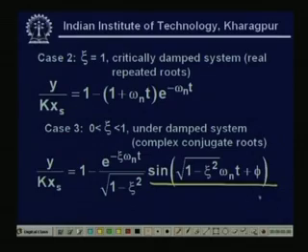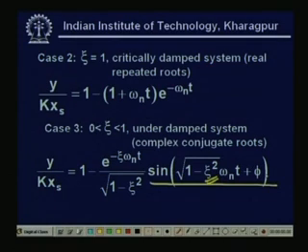How much will be the oscillations? How many hums you will get depends on the value of xi. If xi is 0.1 or 0.01, you will get large hums, otherwise you will get one. If xi is 0.6 to 0.7, it will always be just one hum.